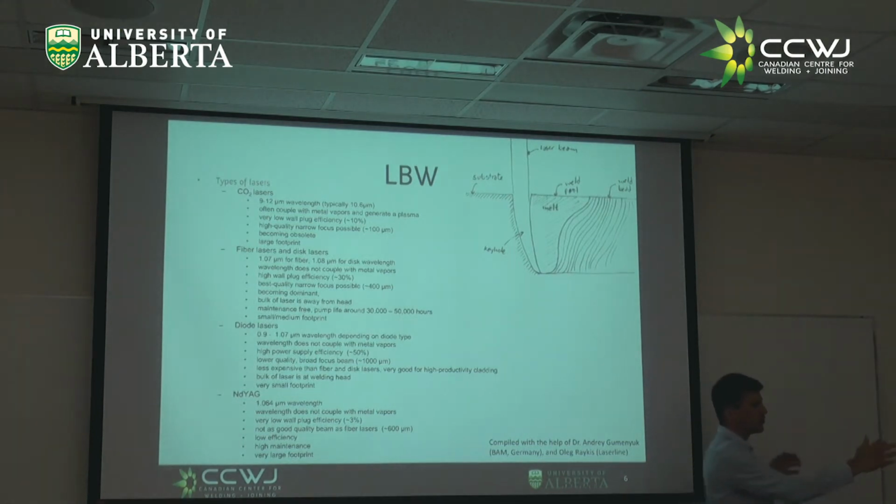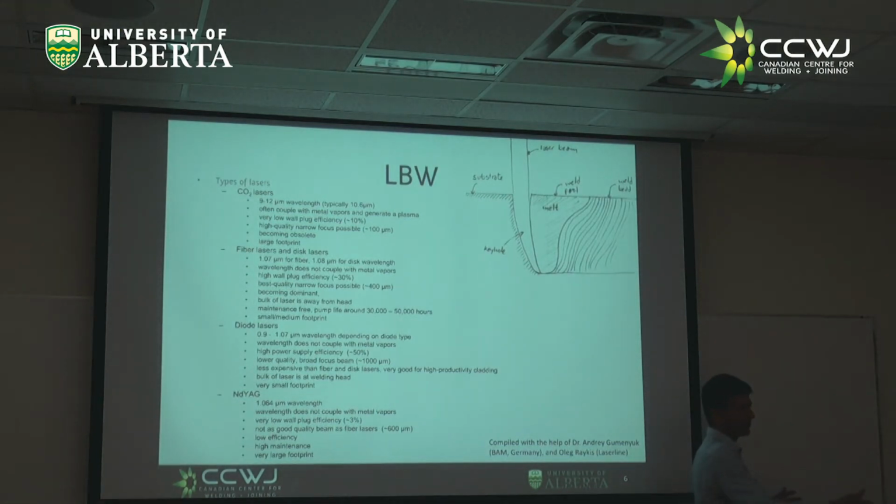Here you have this enormous amount of machinery that is your laser. The light has to go from here to there somehow, and you cannot put an optic fiber because it's not transparent. And typically you don't want to shoot like that because it would be very dangerous. Also, the way welding works, you want to work in the flat position, so you typically want the beam to come from above.